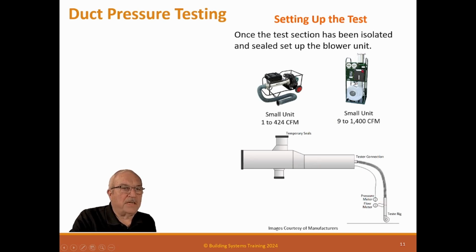These actually take it right at the end of the venturi right here, which is okay, except there could be a little bit of difference between the pressure loss in this duct than if you do it right here. So that's why I always did it that way, so I got the real pressure in the duct.